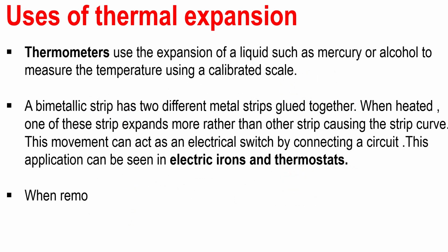When removing a shaft from a bore or a bearing, it can be easily done by heating the bore or bearing.